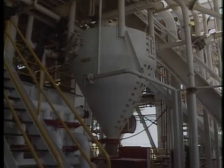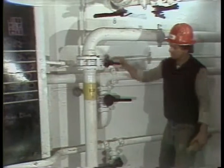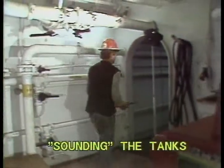It's pretty easy to simply keep track of what you transferred from each tank to the surge tanks, but this isn't really very accurate. At the end of your tower, you need to check the tank or tanks you've been transferring from to see how much physically is left in them. This is called sounding the tanks.